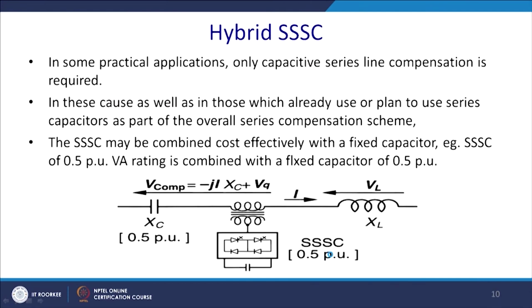So, let us take some practical application of the SSC. In some practical applications, only capacitive series line compensation is required. So, inductive is not generally required and reverse flow of power is also not required. This is just to show, we have shown that curve to show that it has that capability. Yes, it can do that.